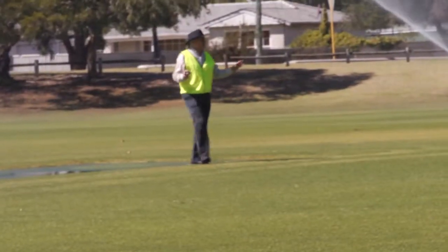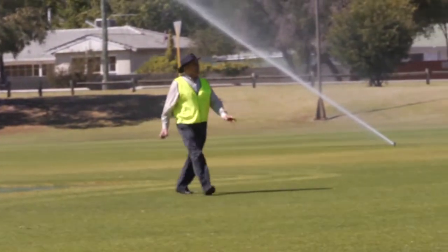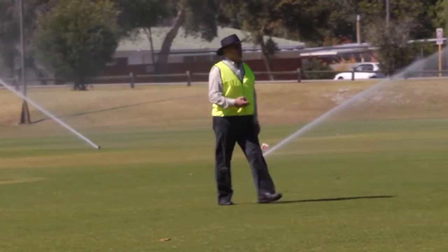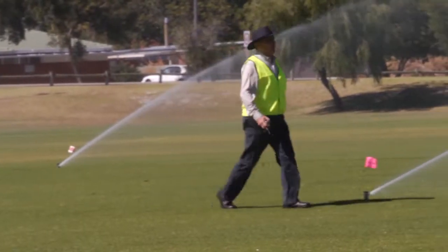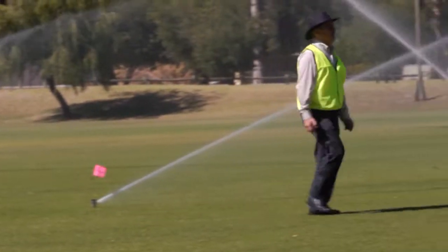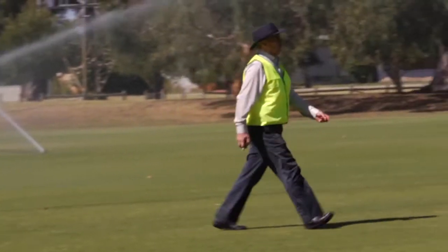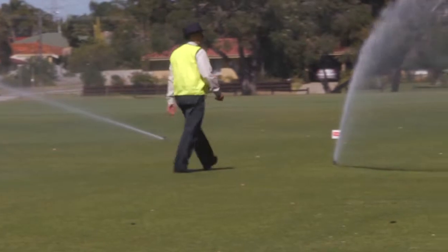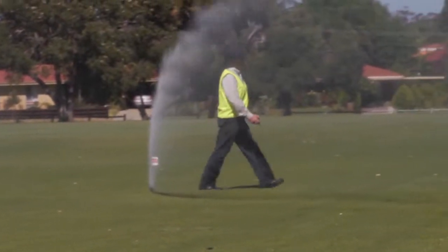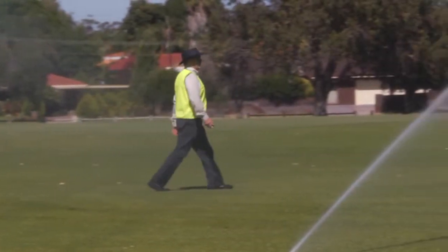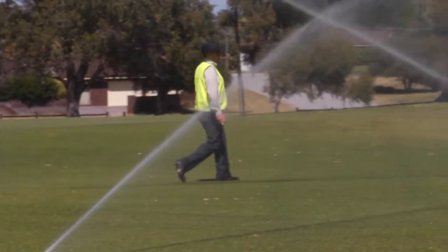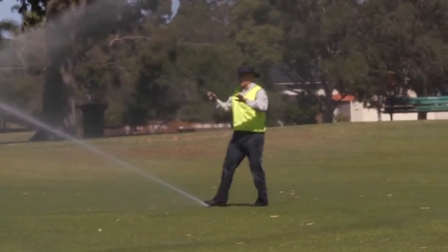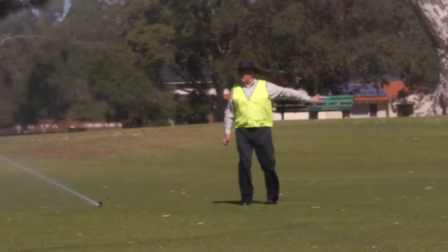You can see just by looking at the sprinklers they're working at good pressure and they all appear to be operating at about the same pressure. And that's just one of the visual assessments you make when you first start the system up. There would appear to be very little loss across the system. On this particular station, there are actually 2 valves operating, and I know from looking at the drawing before we started the test, there's a ring main going around the area, and the solenoid valve controlling this group of sprinklers is located at this end.